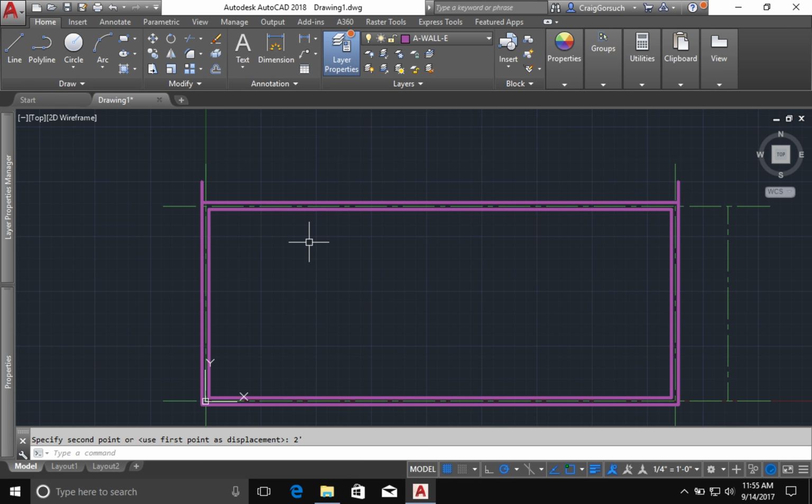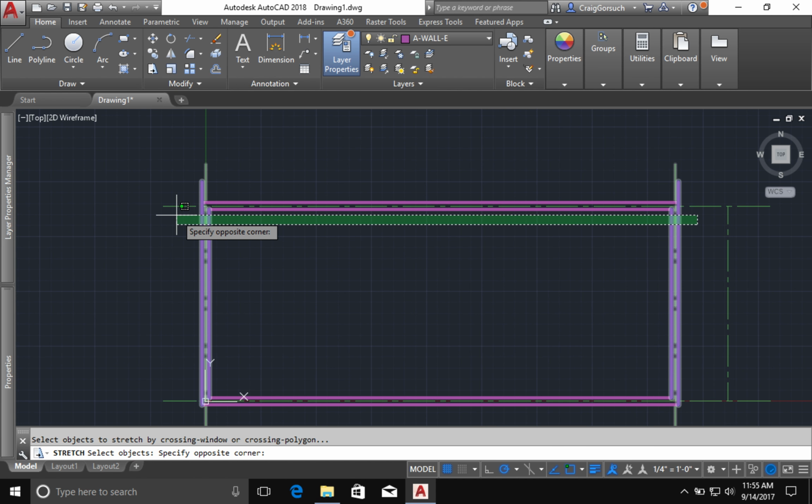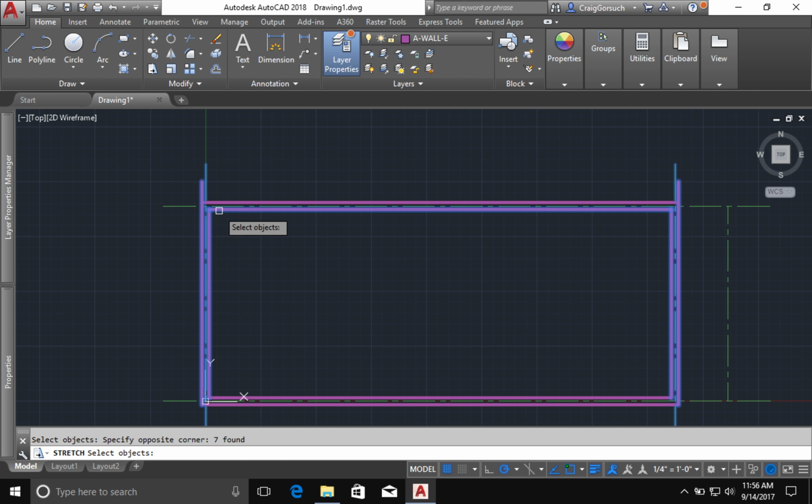So I can use the same trick for the bottom, but then we'll have to add another 8 inches to it. So if I stretch and come from the bottom up across to get the top edge of the inside rectangle, but not the top edge of the outside. So I'll left click and hold my shift key down and select that inside line. I can still do this. I'm done selecting my objects. I can click somewhere out in outer space.